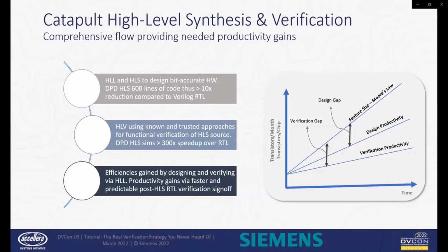And finally, recognizing that today's SoCs are designed using a combination of approaches, including HLS and handcrafted RTL, addressing the verification crisis also means identifying ways to reduce issues in handwritten RTL, such that the fixed simulation cycles every project has can be used most effectively.